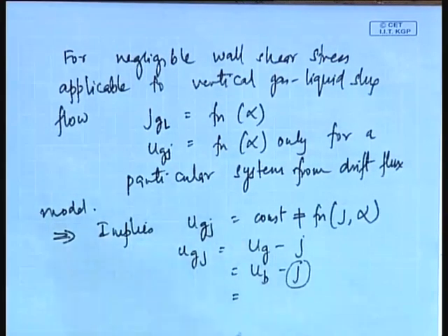That means, suppose in a tube we have just water, the water is not flowing, we have just filled a tube with water and we introduce a Taylor bubble inside the tube. Then the velocity with which the Taylor bubble is rising, a single Taylor bubble rising through a tube, should give me the velocity UGJ, the drift velocity, under all conditions of slug flow. Is it correct? So, therefore, we find a method of finding the drift velocity.